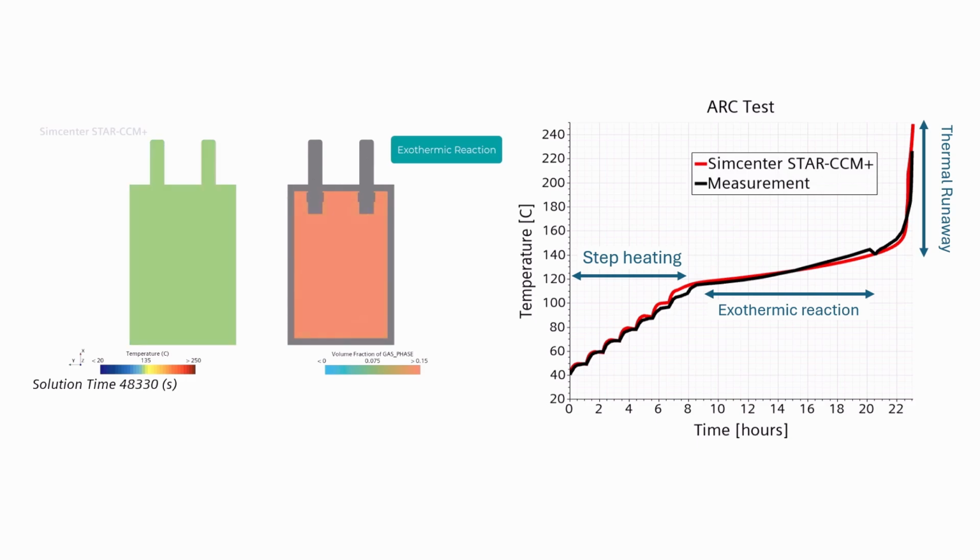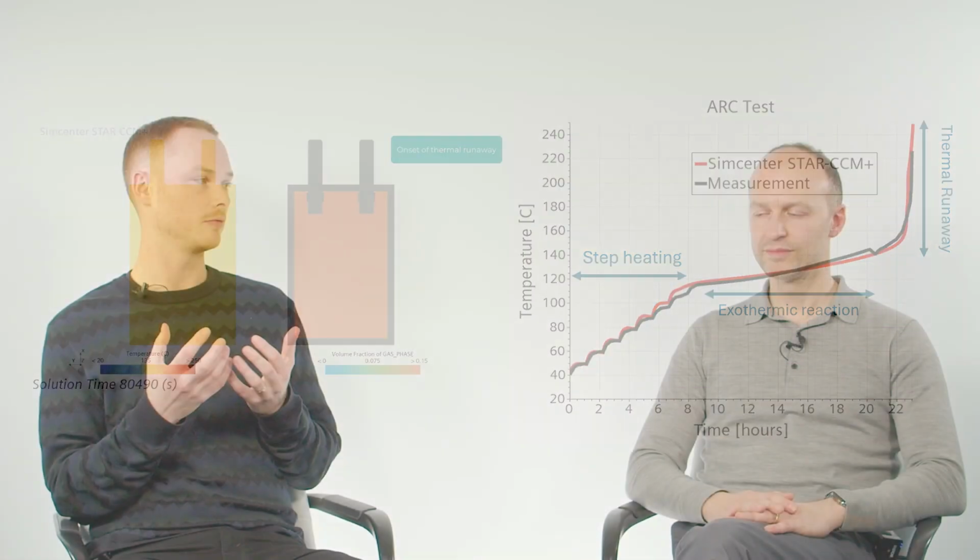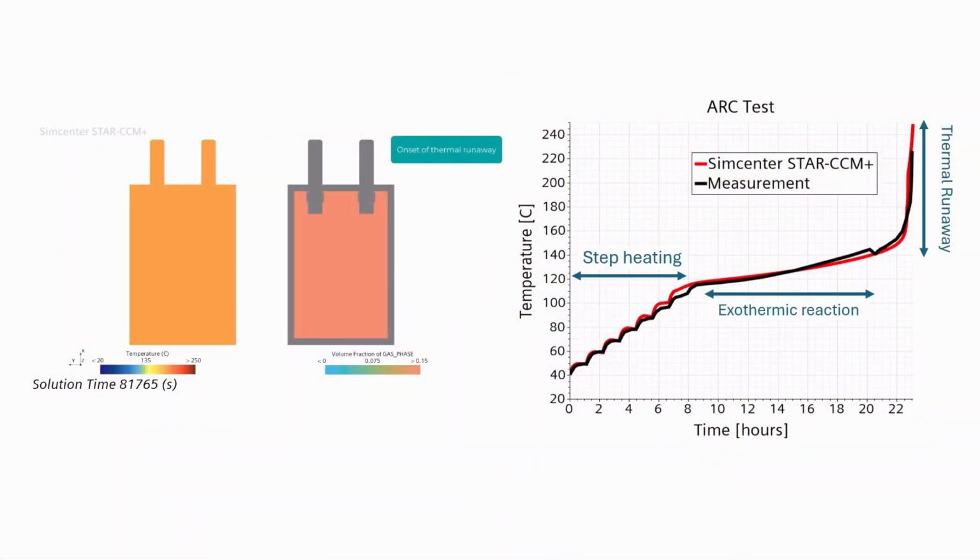These tests themselves are a good way to understand the battery behavior, how it will behave either if it's aged or starts to overheat. And what you want to avoid is that as the battery overheats, this kind of catastrophic exponential increase in temperature. That can be extremely dangerous. It can spread to other cells in the battery and ultimately be a high risk of explosions or danger in a vehicle. So we really want to avoid thermal runaway as much as possible.